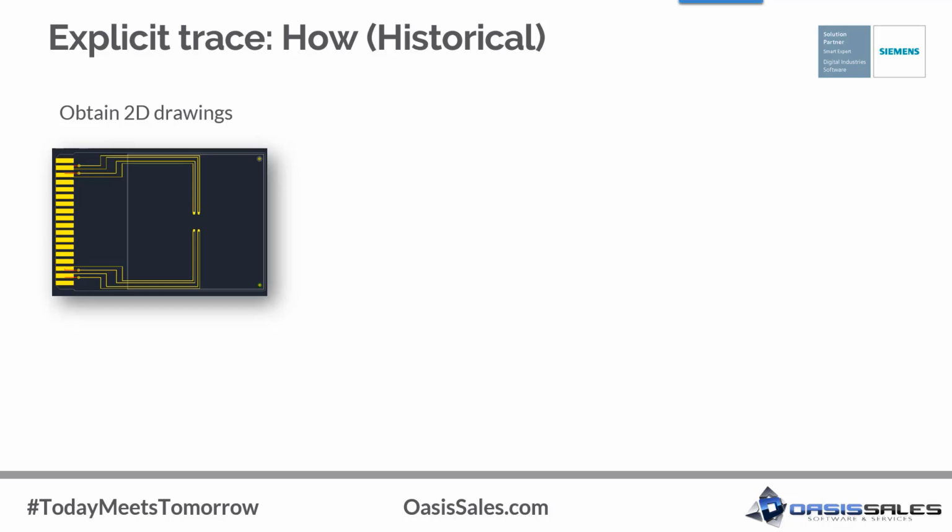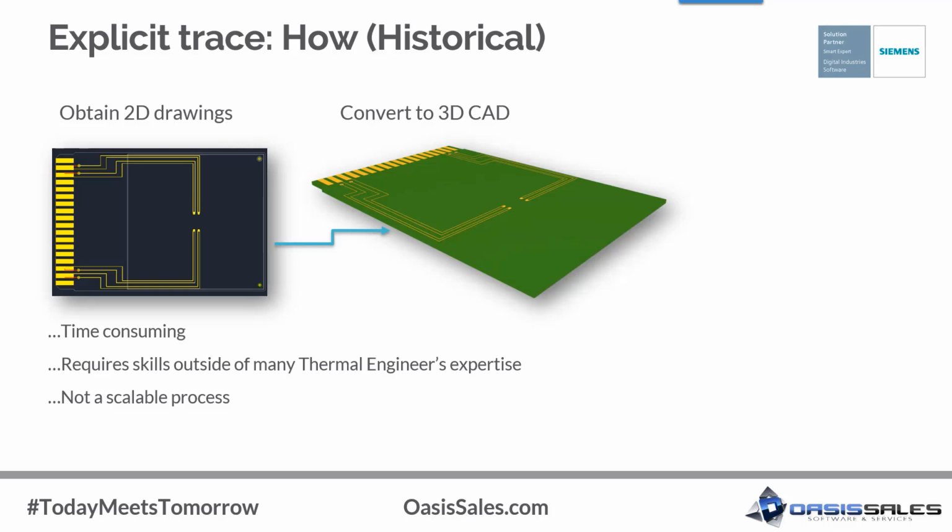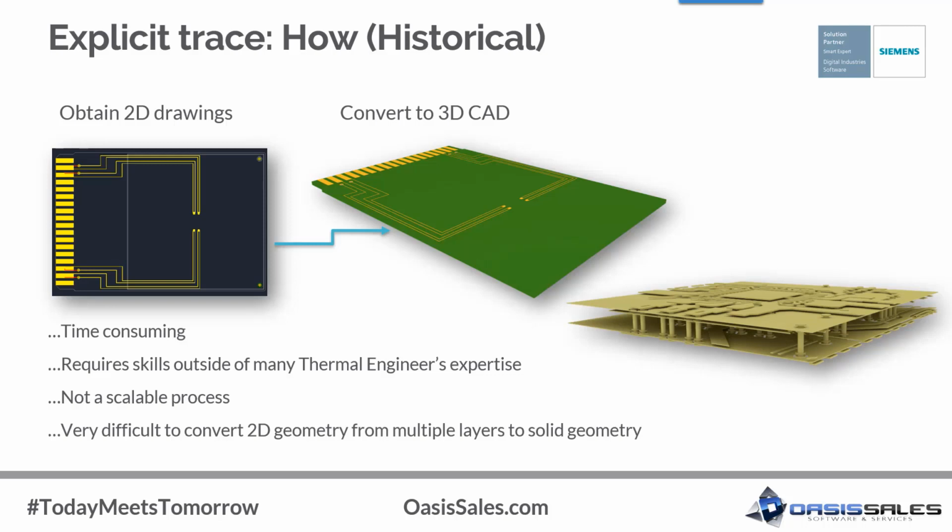So after we have the 2D data, it needs to be converted to 3D CAD through extruding the sketch into a third dimension. Issues with this process are it can take a long time, and each time it will be a little bit different than the previous. A certain degree of MCAD skills are required. If the layout changes, the entire process needs to be done again. Once individual 2D layers need to be connected with vias, the process becomes significantly more challenging. Because of these challenges and others, this process wasn't used very often.